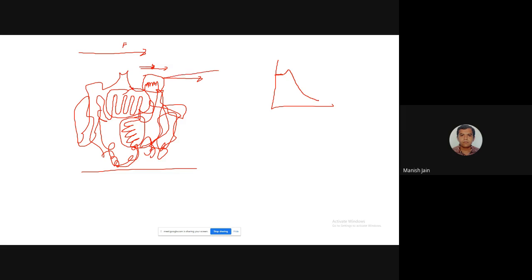Okay, because now the molecules are unentangled. So they will start to arrange in a parallel manner. Okay, and at very high shear rate, since you have removed all the entanglement, the resistance will become constant and the viscosity will become constant. Okay, so you have seen how the complex structure of the polymer affects its rheological or its flow behavior.